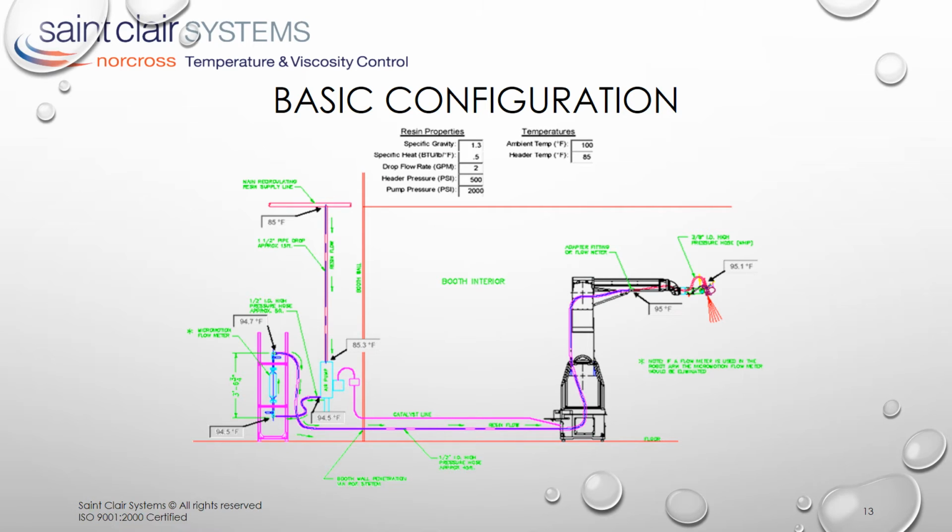throughout the system. Though the temperature may be important at various points throughout the fluid delivery path, to maintain a consistent viscosity and to control pressure drop, there is only one temperature that determines the quality of the finish, and that's the temperature of the paint leaving the nozzle. This is commonly referred to interchangeably as the point of application, point of dispense, or point of use.